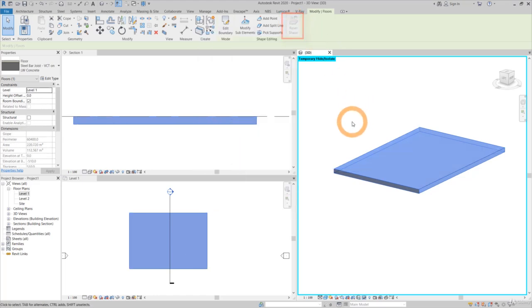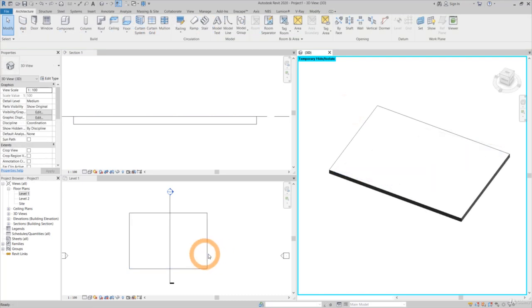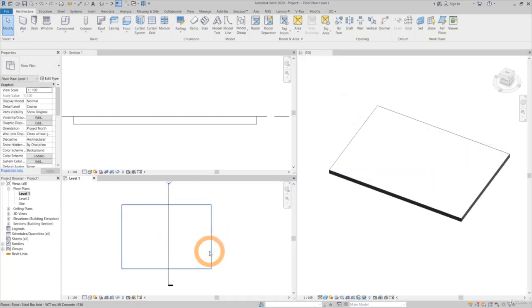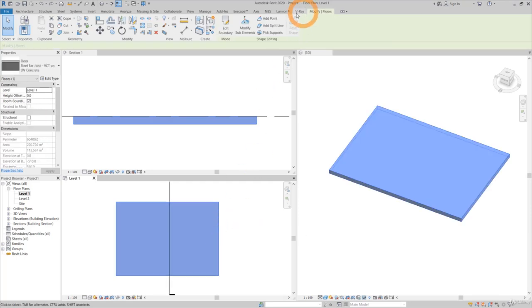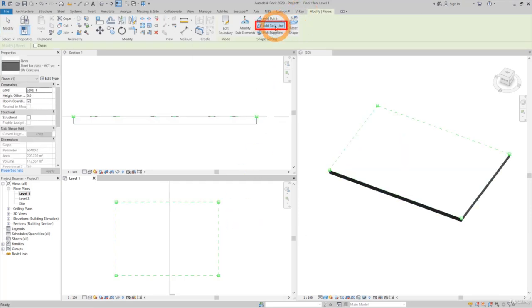Quite often you do not want to slope the whole of the floor element, but just a small part of it. You do this by coordinating the area you wish to triangulate using split lines. Select your floor element and then select Split Line from the ribbon menu. Now simply add lines to section the area of the floor that you are going to slope, then add a point. I have sectioned a rectangular area of the floor.